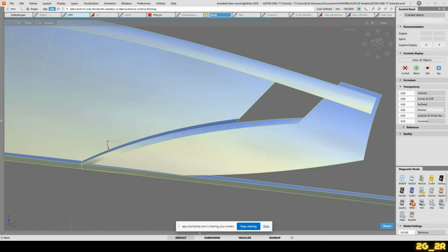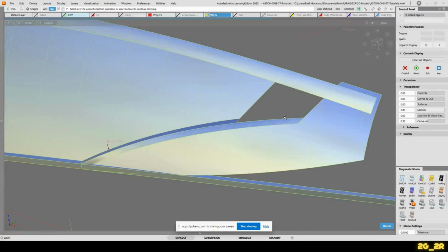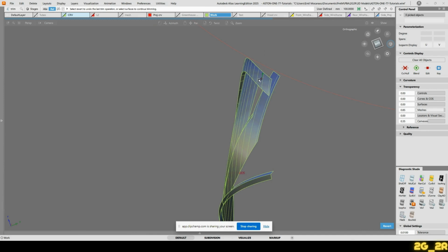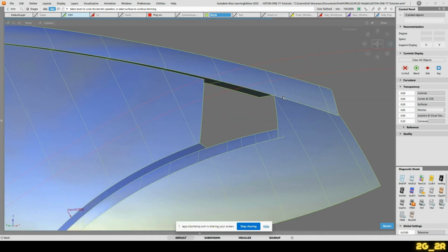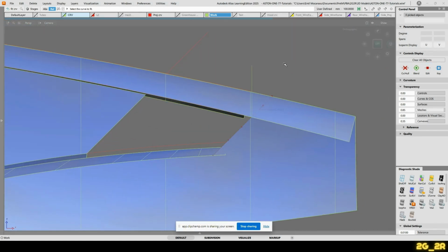What we do know is that we have here blend, and this is going all down there to 0. So we've got a difference in height between the pillar and that, which is given us here by this bit here, that there. So I'll fit curve this here. I'll extend that back to that point there. Turn this curve into a degree 3 curve.